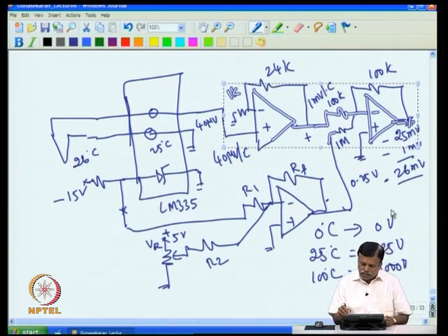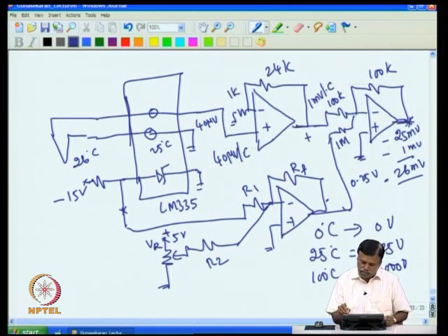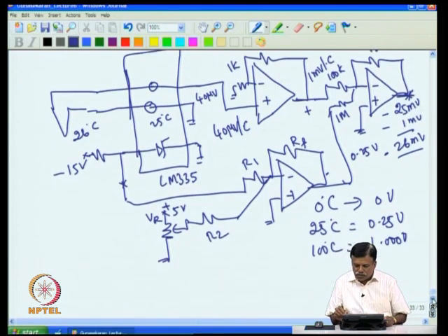So you will get at this point voltage corresponding to the temperature, and this ambient temperature compensation is a must, because nowadays in industry no one uses a dual junction thermocouple, everyone uses only single junction thermocouple. They always give ambient temperature as a compensation in this manner. So now what we have done is we have got output voltage corresponding to temperature.